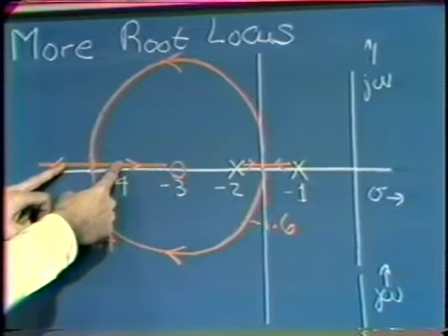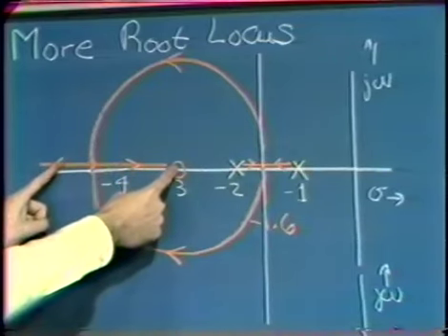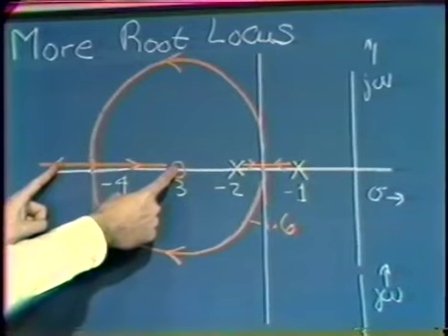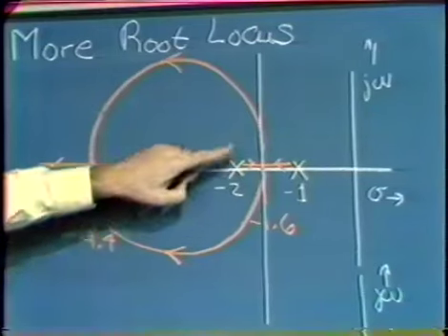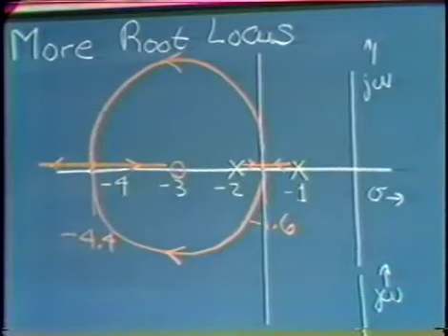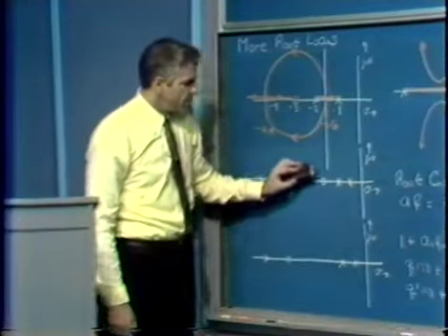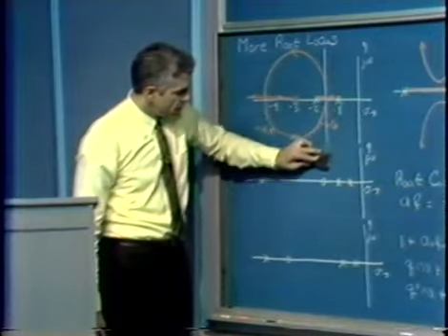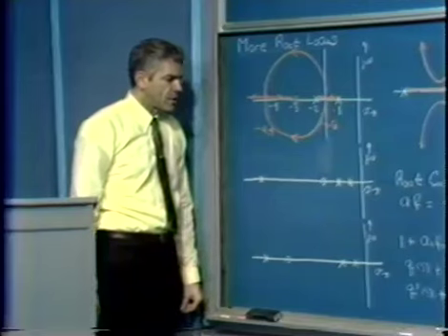And so now we have the overdamped situation. We have no overshoot at all in the step response, no peaking in the frequency response. So the important point is that adding the 0, assuming we're able to do it in view of other system constraints, allows us to get much higher values of desensitivity, much larger A0, F0 products, without running into any stability problem. And that theme continues for many, many other loop transmission pole 0 configurations.